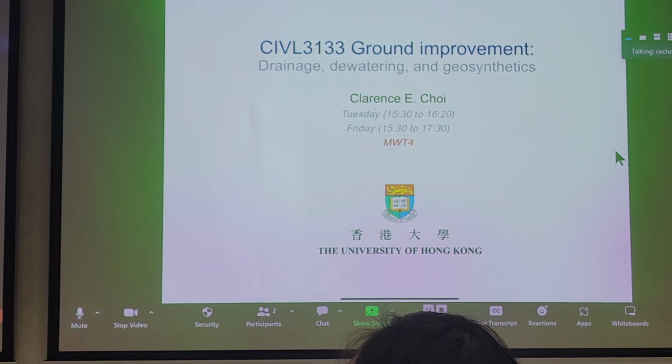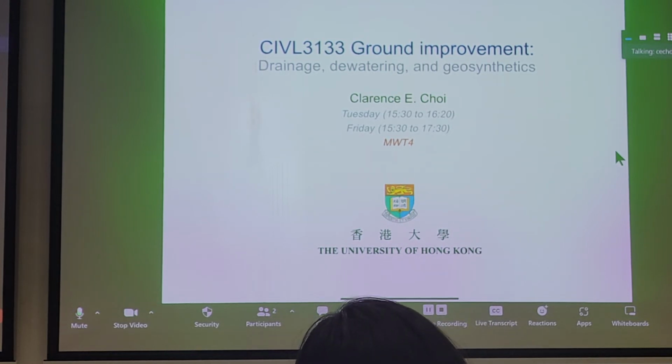Well, we understand geotechnically that if we can reduce excess pore pressures, we can increase effective stress. And by increasing effective stress, we can increase the stiffness and strength of the soil. So dewatering and drainage is a very significant component for geotechnical engineering. Particularly for most projects that are in coastal areas, we need to dewater. And for the various types of ground improvement I talked about, for example, over-excavation and replacement, if the groundwater table is too high, I mentioned we have to dewater first. So conceptually, we can talk about it.